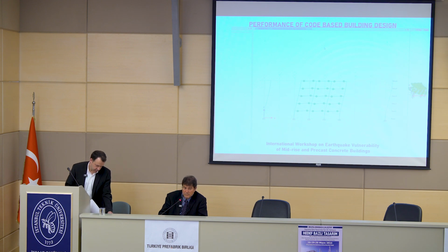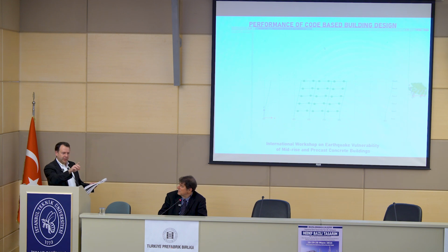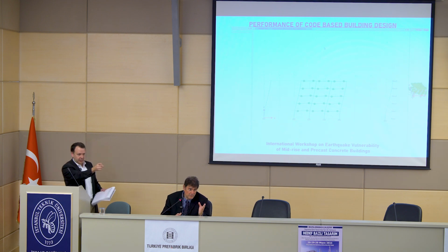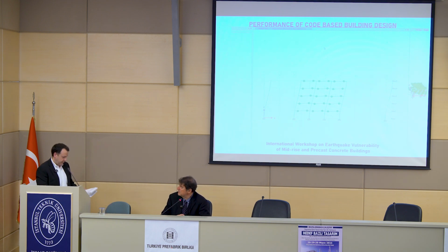In the Turkish design, what was the base shear that actually developed? I took some notes, and please correct me if I'm wrong. For the same load, I had from your design 0.088 in the X direction, so about 9% in the X direction and about 10% in the Y direction. Is that correct? Yes, I think so. If I remember correctly.